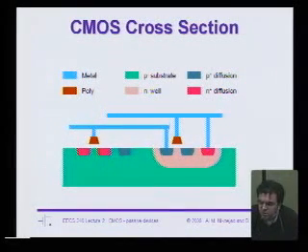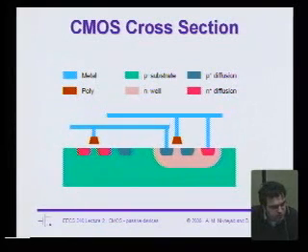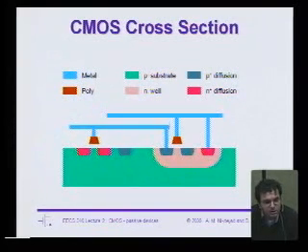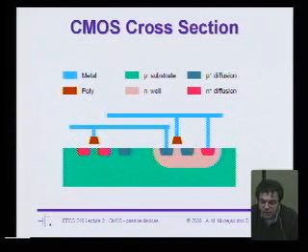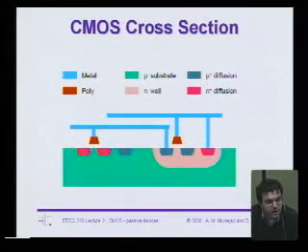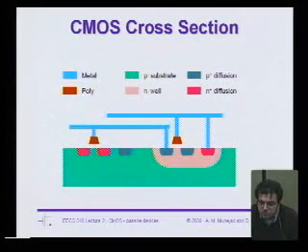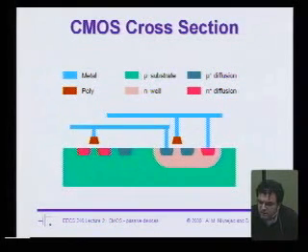In a traditional CMOS process, your NFETs are actually in the substrate, right? And so their body contacts are all necessarily grounded. And so if you have any NFETs that are not basically source at ground, you have body effect. So just remember that when you're doing design in what we call a single well process.